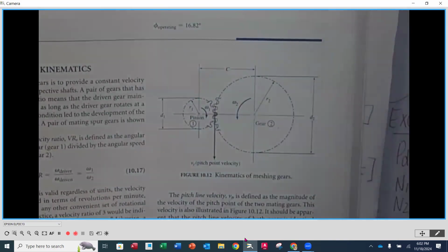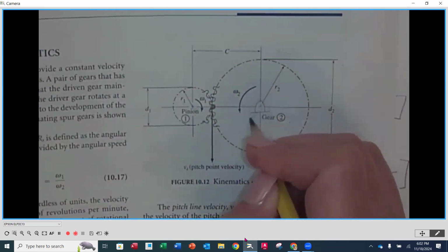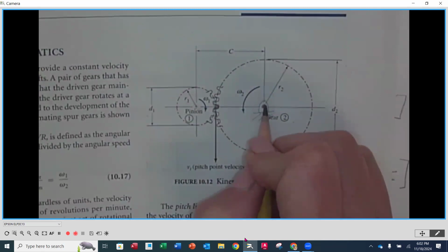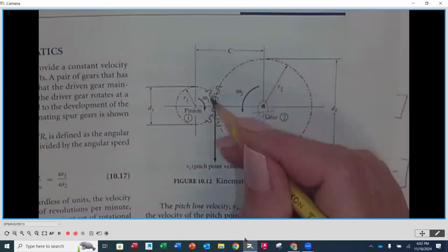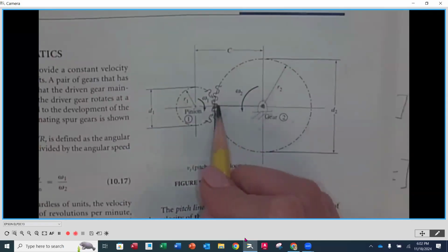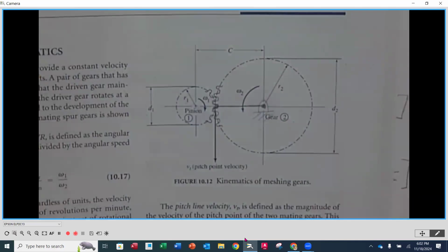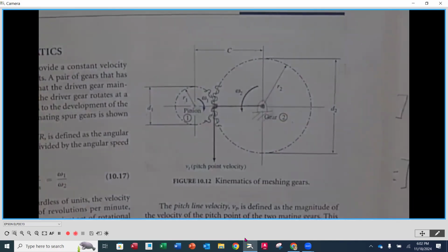Now, what I want to show here is, imagine the center of the gear, the center of rotation. Let's say that that is the frame. That's not going to move, and a lot of times it doesn't. If you remember some of the kinematic diagrams that we did that had a circular element, like a flywheel, we would go from its center of rotation and just draw it as a link to where it would connect. Well, in this case, it might not physically be a pin that connects them, but we have connection between those two as they rotate.